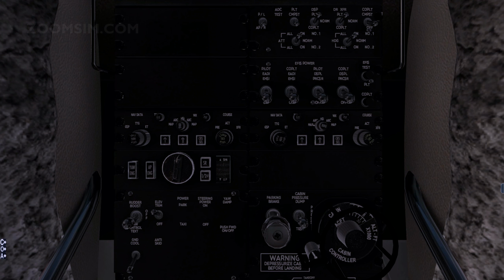Before takeoff, the cabin altitude selector should be rotated until the aircraft scale indicates an altitude approximately 1,000 feet above the planned cruise pressure altitude, and the cabin altitude scales indicate an altitude at least 500 feet above the takeoff field pressure altitude. During descent in preparation for landing, the cabin altitude selector should be set to indicate a cabin altitude of approximately 500 feet above the landing field pressure altitude.